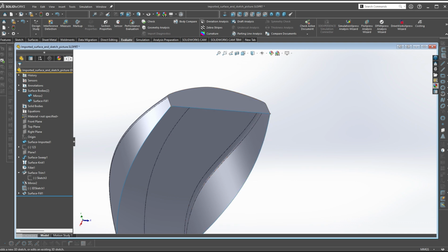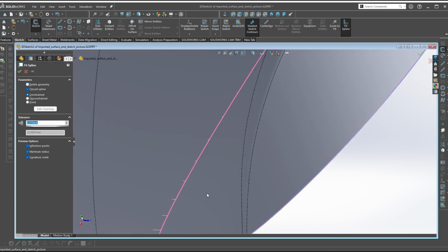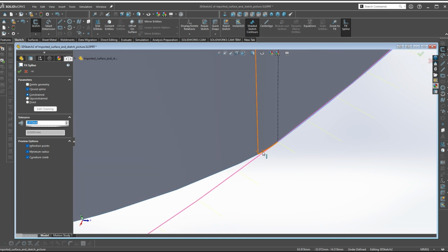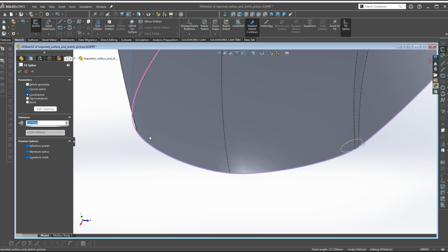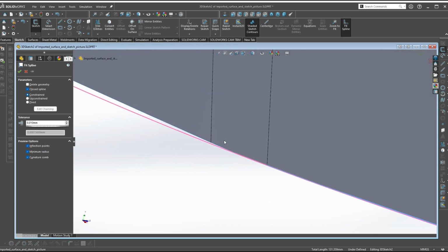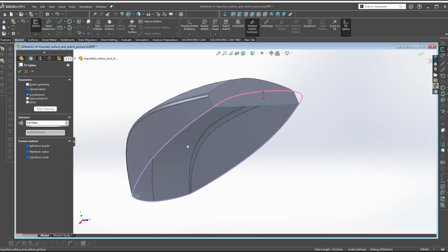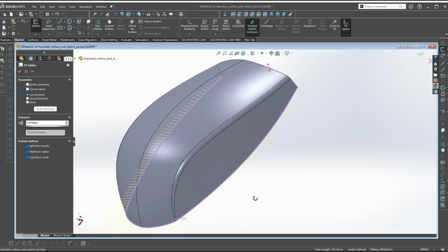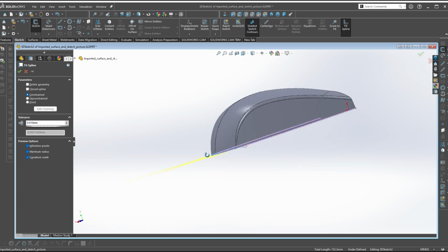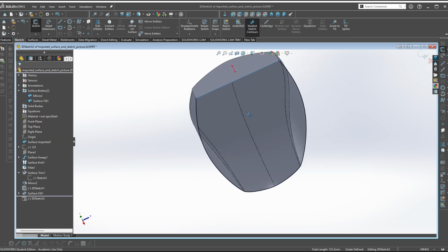So let's create another 3D sketch, and we're going to Fit Spline again. We're going to start here. You can see the nature of this. You've got a little tag here, so let's make sure you click this here, here. Okay, kind of hard to see in there, but we're going to grab that edge right there, and then this. That's going to bring us all the way to the front, and let's go ahead and open up that spline in this case again. Okay. In this case, it's putting the little comb marks out to the side. You guys can see that. Okay, and when I approve this, that spline is dropped into place.